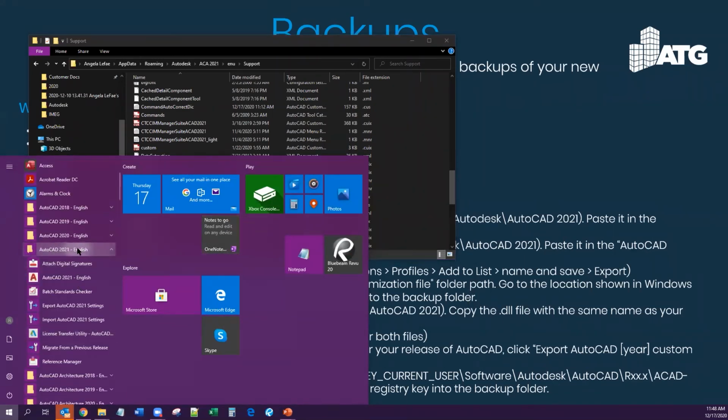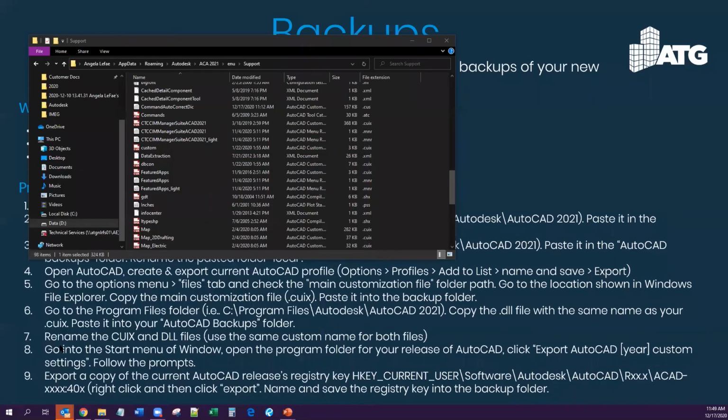That's why I showed you the manual backup steps and talked about that stuff, because you may want to bring, say, AutoCAD stuff into Plant 3D, and you can't do it with this automatic wizard. There is a migrate from a previous release, which is really nice. If you say AutoCAD 18 is customized, I just put 21 on here. The first time I open it, this migration will pop up, but if I skip through it the first time, you can go back and launch that from the Start menu.